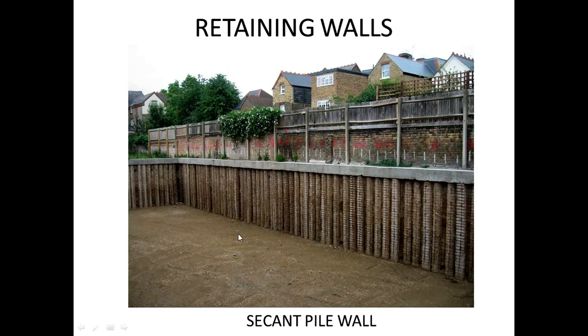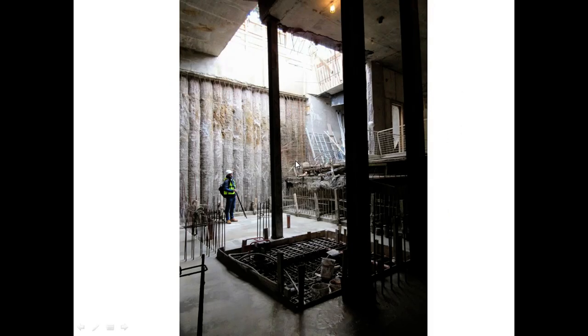And you can either then build out of this hole here, take the load back down into here. You might again even have piles or pads, or even a strip foundation down here. Or if you want to, of course, you can build straight off that retaining wall. You can build off that pile cap, can't you? Here's an example of it underground.